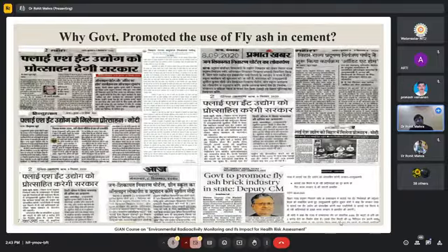And second, the strength got better and the leaching properties decreased. So the tiles which were not sticking to the OPC cements during their panel work or batch work are now more sticky to the cements. That enhances some of the constructional parameters. That is why the government gave a lot of initiatives to use fly ash in the cements.